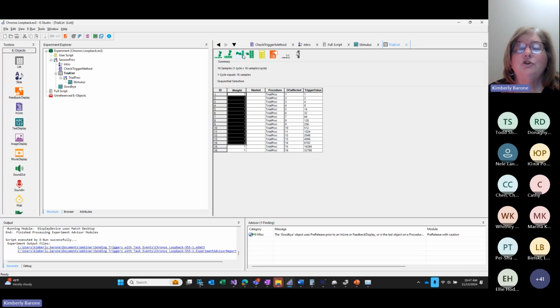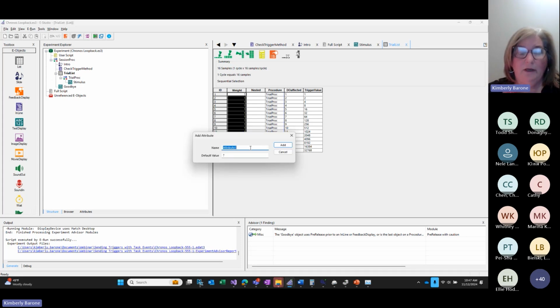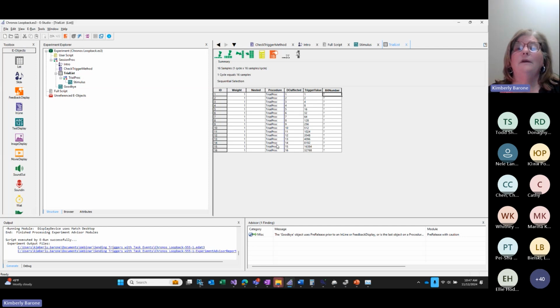I wanted to just show you. I don't think we're going to have time to run it, but I'd like to illustrate if we wanted to change this, instead of calling write integer, we wanted to call one of the bit specific methods, what value we would put. So I just created a new attribute called bit number. And I'm going to specify a 14 and a 15 here. Because again, the bit numbers are 0 based.